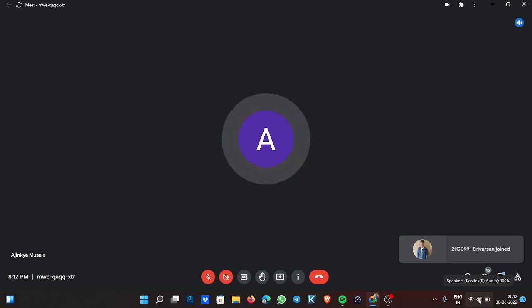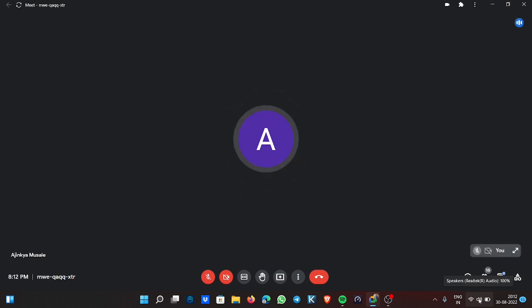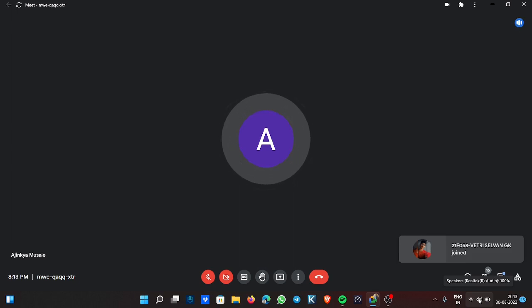When you click on Workbench, this window will pop up. This we call the project window. In it you have the file, view, tools, units, and extensions menus. From that, your first step should be to check units. I checked it, and I want it in metric.